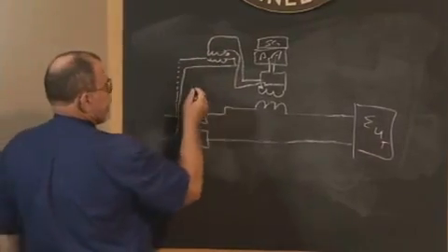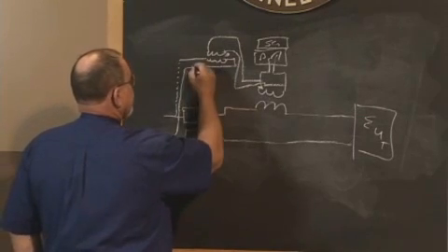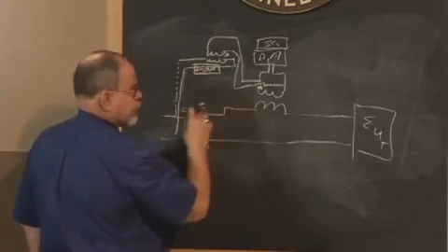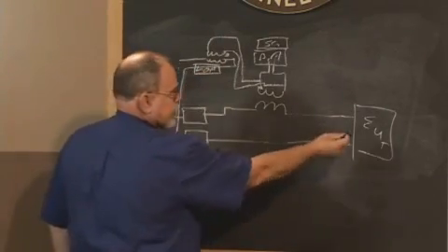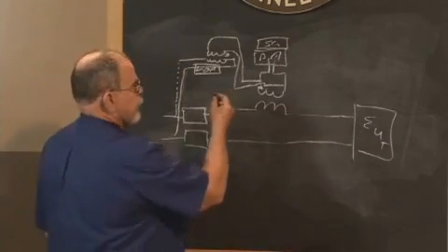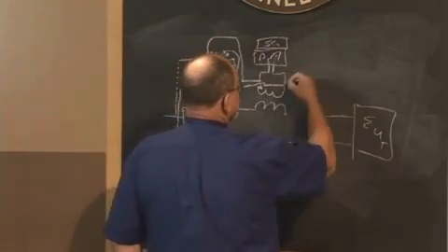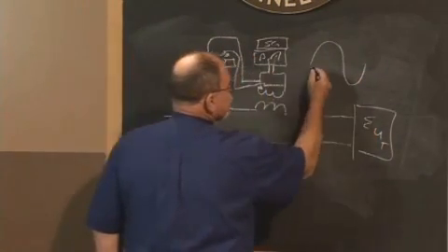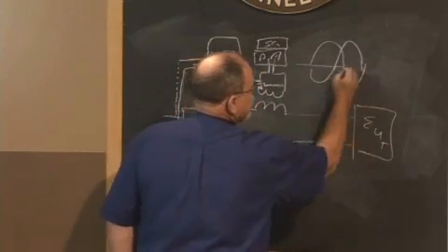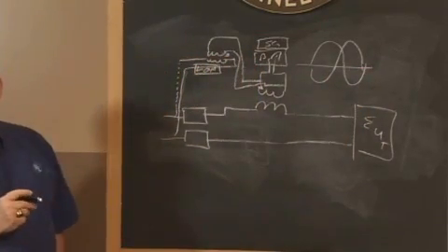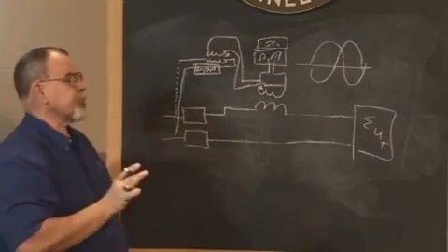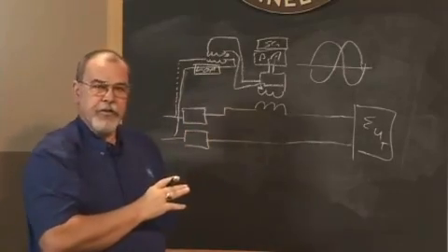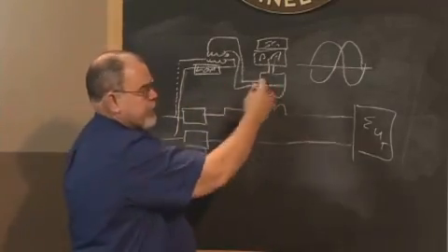We put a dummy load on this circuit for the power, a load of some sort that emulates the test article. So this load circuit is drawing the same current as this load circuit. So effectively what I have on this side, the 60 hertz being fed back, is that waveform. The 60 hertz being fed back on this one is that waveform. So we have a net cancellation. Ends up with 0. This is how it's described in the MIL standard, providing this type circuit. The figures are obviously much more cleaner in the standard. But the idea is that should work.